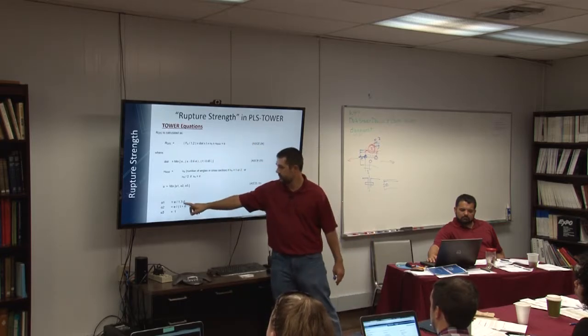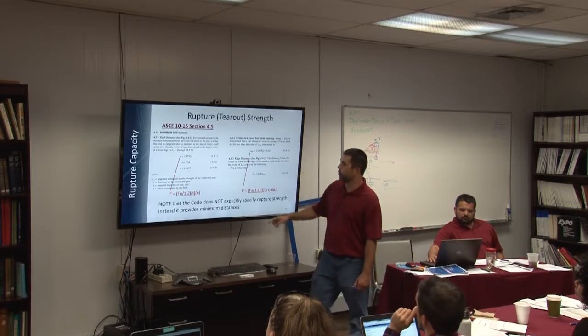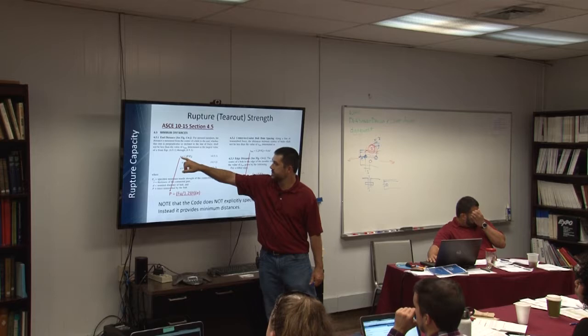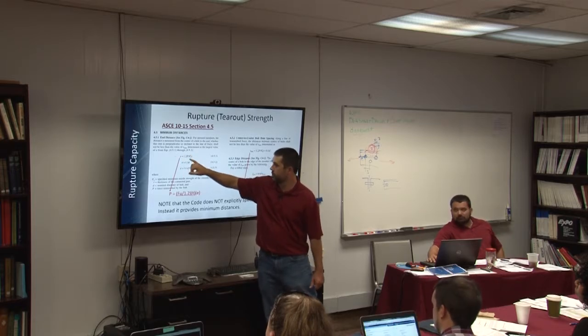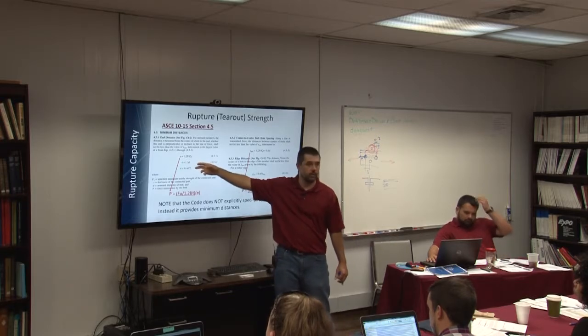And they do the same thing with this kind of thickness requirement. So you can go to the next one. In other words, my end distance based off load is based off this equation. But if I haven't met this stipulation, then they decrement your load by a ratio.